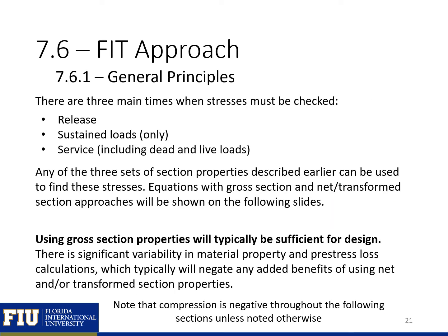There are three main times when we need to check our stresses. We need to check them at release or transfer. We need to check them under our sustained loads only, so our pre-stressing, our self-weight, and any superimposed dead loads. And then we also need to check them under all of our service loads, so under our pre-stressing, self-weight, superimposed dead loads, and our live loads.